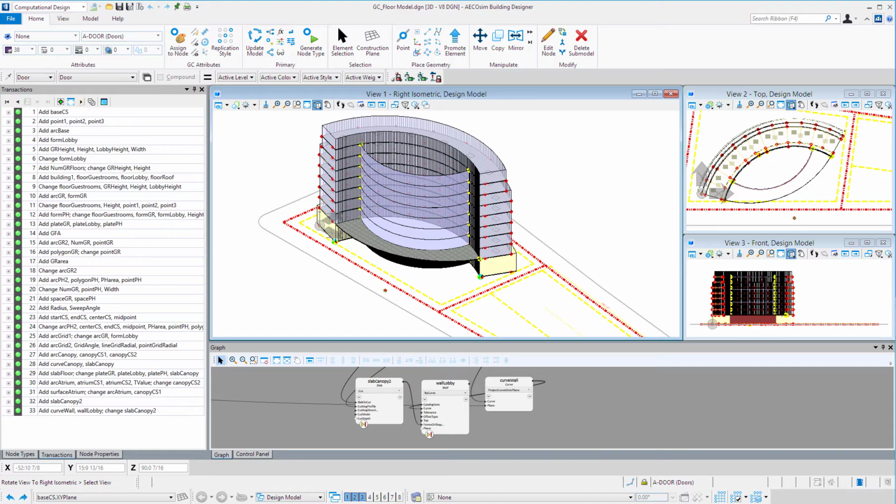So what if you could start and end the arcs at different points so that you might create a more interesting facade? What if you could create a slider that did not provide a constant variable, but rather a list or array of related values or variables? So that's the purpose of a law curve. A law curve actually graphs the values on a curved graph.